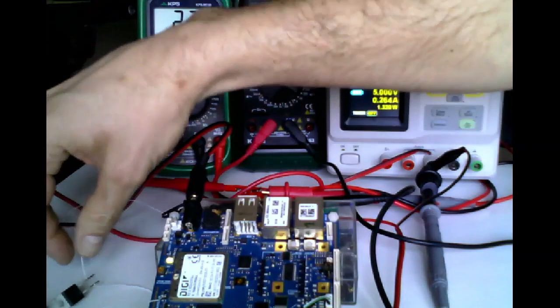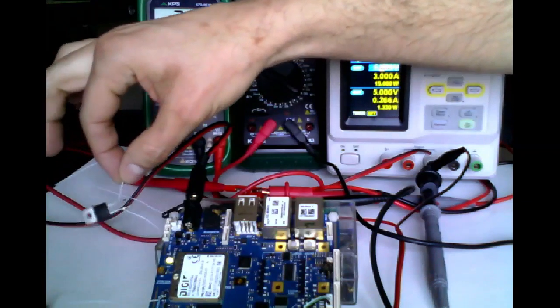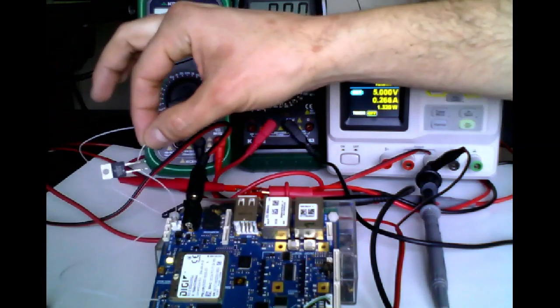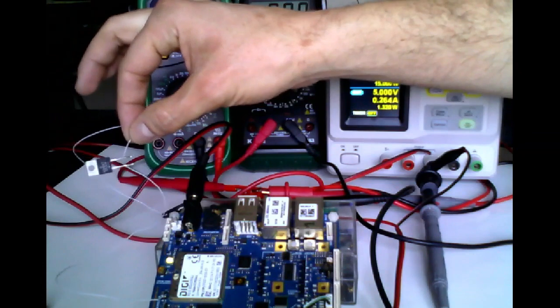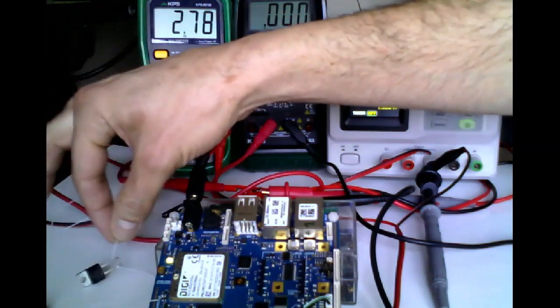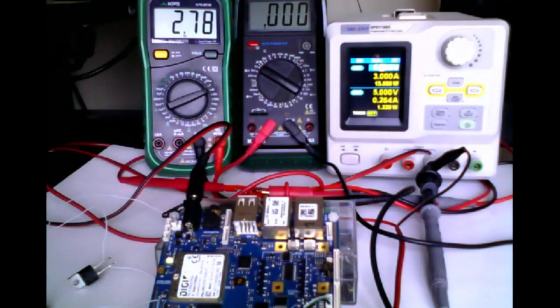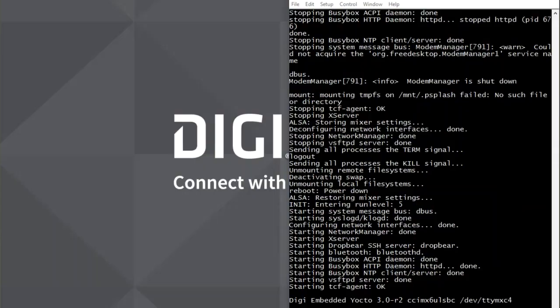I would like to show you also that this is my external Schottky diode. Of course, it's a huge Schottky diode, but it is still valid because it's Schottky. Okay, so the message is try to keep as low a voltage drop in the diode as possible in order to save as much energy as possible of your battery or coin cell.